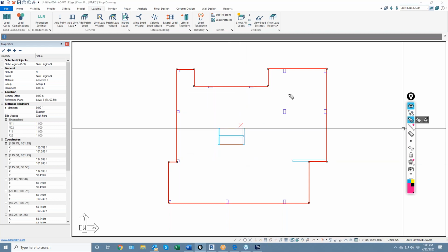Once we get downstream into the presentation, we're going to have design strips set up, and in each design strip we're going to define a span. So you're going to have, for example, a point here at this column, maybe a point at that wall, a point there, and a point here. This is span 1, 2, span 3. When we add post-tensioning in the slab, the program is triggered to generate the solution, for example, for load balancing percentage.